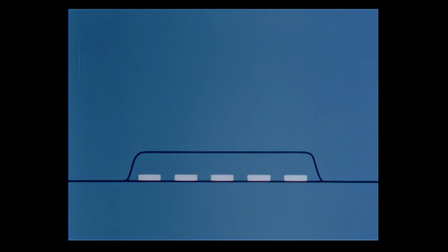Broadbanding in this region enables us to handle a number of carrier frequencies. As before, we must lower the antenna's Q to achieve this broadband requirement. Broadbanding in the microwave region is easier to achieve. Because of the smaller wavelength, our dipole is physically smaller, and we can lower its Q by increasing its rod diameter.